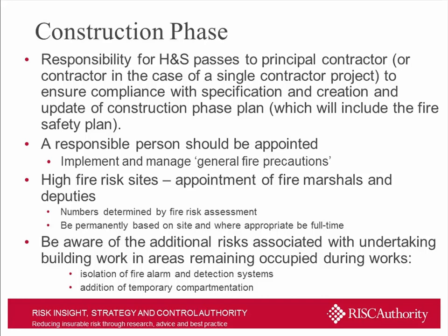But I think what the code is trying to focus on is the requirement for there to be somebody who's nominated to be in charge in real terms. So there's a focal point for fire safety. And it's their responsibility to implement and manage the general fire precautions across the site during the construction phase. Not always, it sounds very easy in that respect, doesn't it? But I think we all understand that the construction environment is very much a movable feast. Nothing's the same from one day to the next, and the management of fire safety can be a far more, I suppose, fluid requirement than it would be in fixed, static and occupied premises.